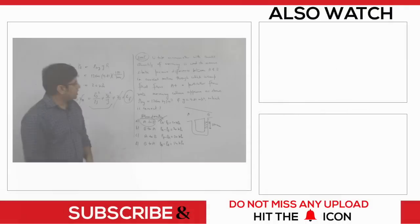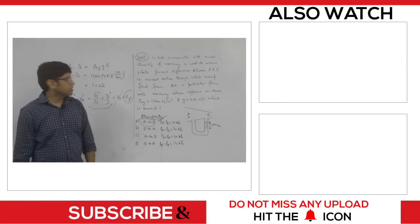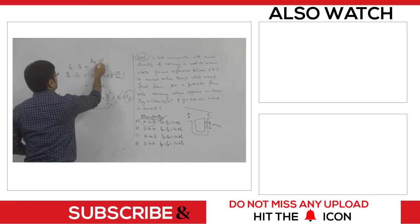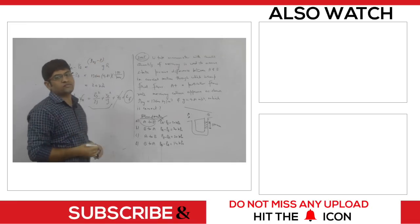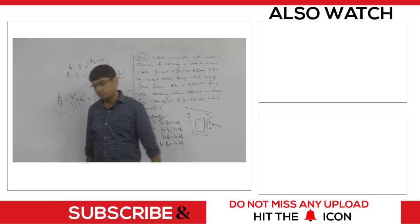Another thing I want to add here: suppose he has given you the density of the fluid which is flowing also, then in this particular equation you have to write rho mercury minus rho, into g h. That is the only difference which will come. Then you could have calculated the difference of pressure like this. Fine, just note it down.